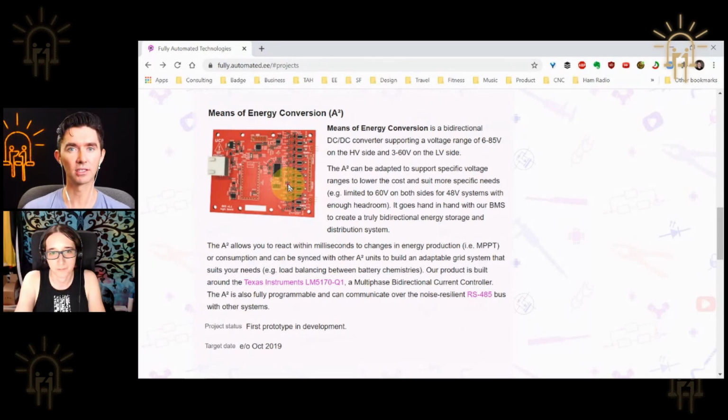Are there certain design considerations that you've learned from that? Yeah, definitely. So we tried out a few things, and also to keep the costs down, because we couldn't just go with 4-ounce copper PCBs, because that would have driven the costs up way too much. Right, a full, pure solid copper PCB.